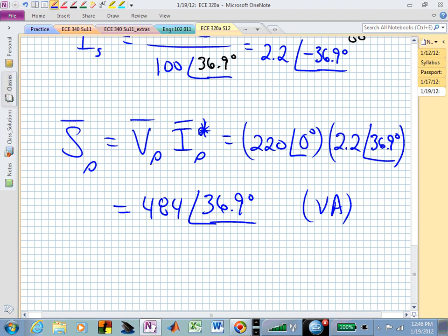That's the conjugate. So when we conjugate something, that's when we have to change. So if it was in rectangular form, you have real plus imaginary. When we conjugate it, it's real minus that imaginary. In a polar form, all that means is we change the sign of the angle when we conjugate something. Yes, so we're taking it from a 36.9, now we're going a minus 36.9 if that was our orientation. Is that okay? And we started at minus, didn't we, with the current.